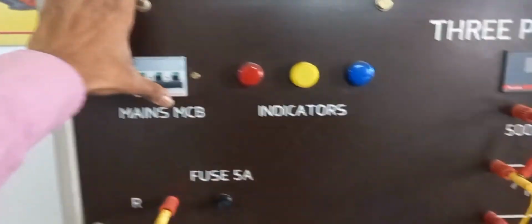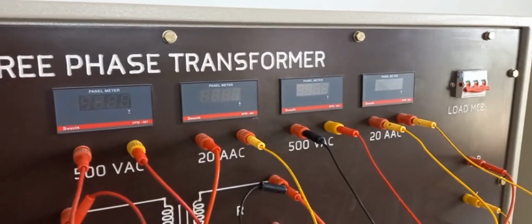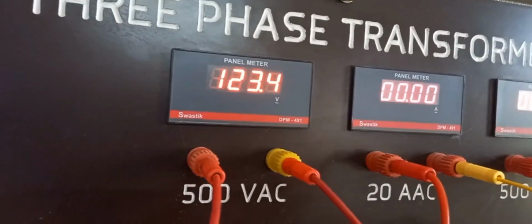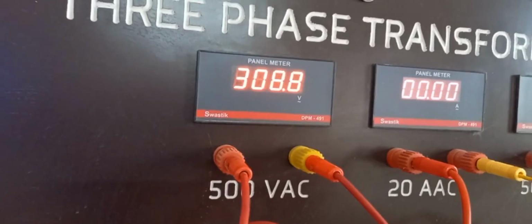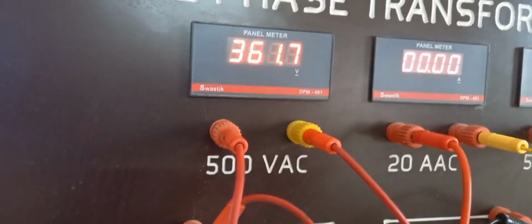Then we will turn on the power supply. So after connecting the 2 ammeters at primary side and secondary side, I will vary the source voltage by using the variac. By using the variac I am going to vary the voltage up to 400, because the range of the transformer is 400 volts.